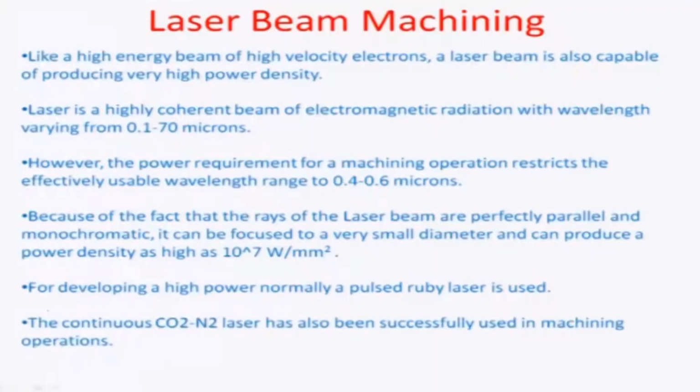The phononic vibrations result in a local temperature increase, and there is a big issue of reflectance in the laser machining process, because extremely reflective, smooth surfaces have a lot of power loss induced by the reflectivity, which results in effectively utilizing a very small percentage of the laser beam. So in order to investigate the laser beam machining process, one needs to really look into the fundamentals and basics of laser. Laser, as we all know, is light amplification by stimulated emission of radiation, and let us look at some of the properties of what a laser beam is capable of.